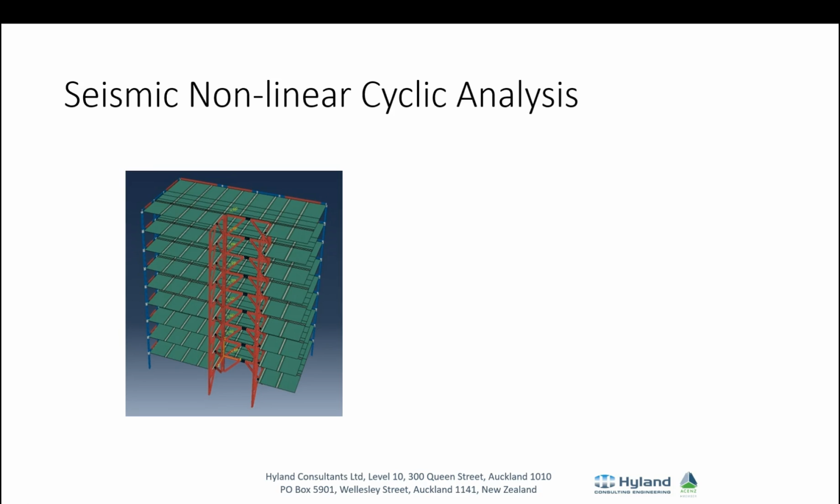Another thing we've used it for is cyclic nonlinear analysis and seismic. So here's a building that we analysed. It had been through an earthquake, and there were some questions about the deformations of the EBFs, eccentric brace frames, and whether or not these could be repaired, or whether they could take another similar size earthquake.